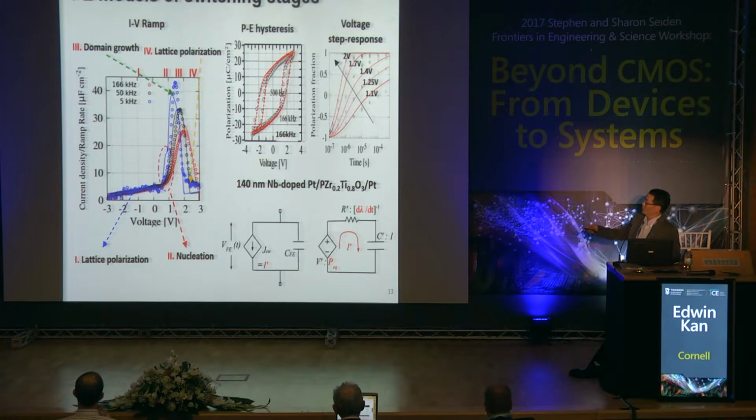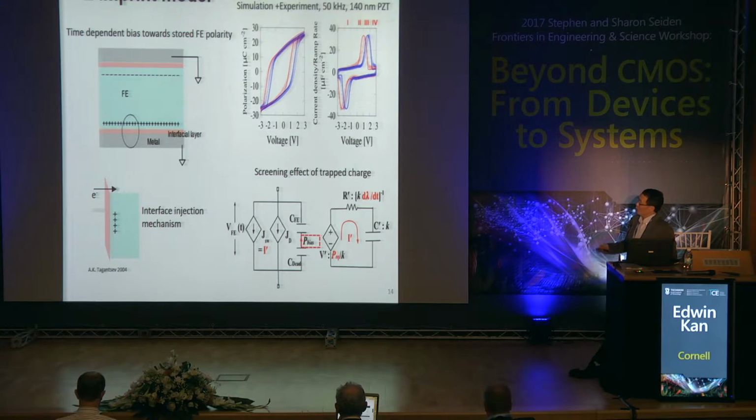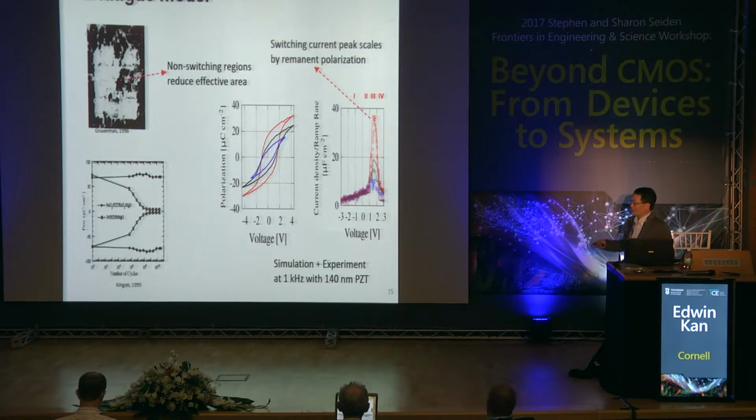So there are 4 distinctive stages of ferroelectric domain switching, and we can capture that with an easy SPICE simulation. Once you have that, you can add your imprint and your fatigue. Those can all be represented well in the circuit model. So now you can have a SPICE model, entirely continuous, with no surprises in any region. You can deal with your ferroelectric hybrid CMOS.